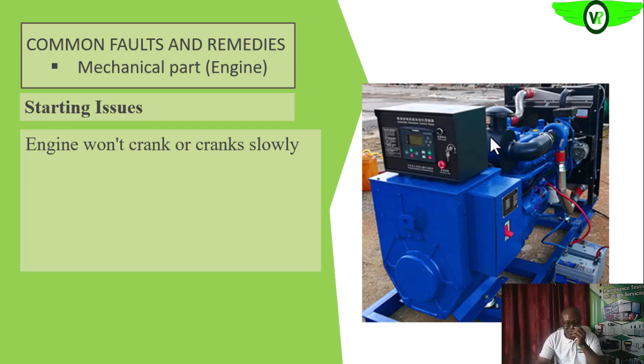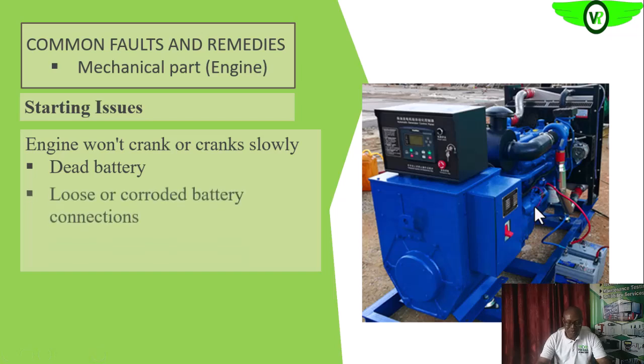The engine will not crank, okay, or it may be cranking slowly. Are we getting it? So what could be the possible reasons why they are cranking slowly? So if you look at the right, you see that we need the battery to actually drive the starter motor. Okay, so it is possible that this battery has no power, is dead altogether. We are very familiar with that. So there will be no energy available for the motor, the starting motor, to do its job, to turn. Okay, that could be one.